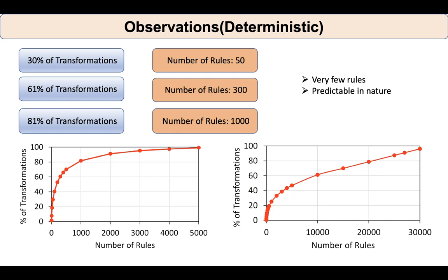In the previous section, we have established that the changes induced by logic locking gates are local and limited. Let's go one step further. Given the designs before and after synthesis, if we measure each transformation, we will observe that very few rules are used by the synthesis tool for carrying out most of the transformations.